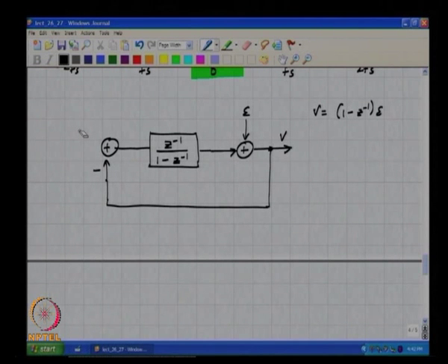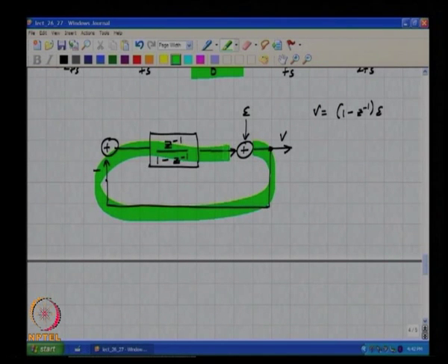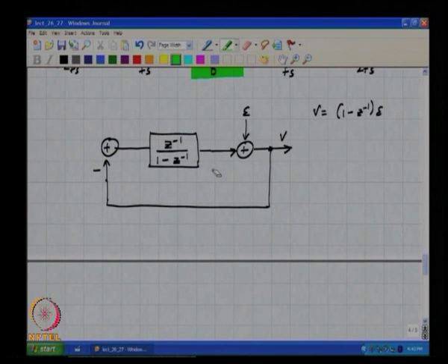We want to make sure, see, the feedback loop is this way, correct. So, if you want to realize the same noise transfer function with continuous time circuitry, we should focus on this whole path, that is, you break the loop here, for example, you will get the same noise transfer function if you have the same loop gain, correct. And how will you measure loop gain? In this example, I will break the loop, okay, like this, for example.